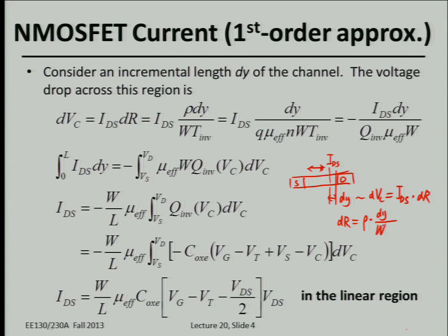For the MOSFET device, think about how the current is going to flow in the MOSFET. The cross-section would be the channel width times the inversion thickness. Although we know that the inversion layer would be very thin compared with the depletion width in the MOSFET, we're still going to assume some finite value here for the total thickness of your MOSFET conducting channel.